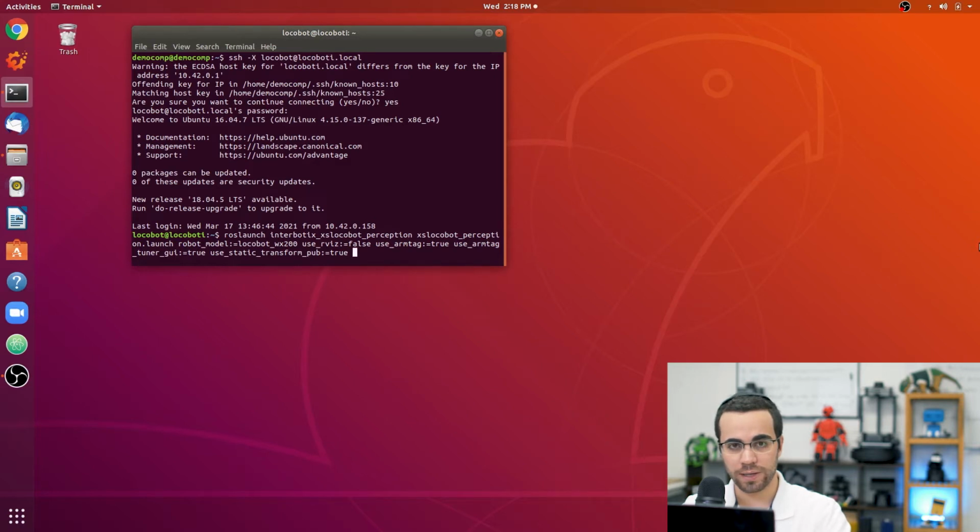As you might know from the standalone arm vision kits that we did a tutorial on, the ArmTag related nodes are there so that you can figure out where the arm is with respect to the camera. In the case of the LoCoBots, though, we already have a URDF that defines this, so we don't really need to do calibration. The only reason you'd want to do it is if maybe you want to get some better accuracy, finding out what the pose is of the AR tag with the camera directly, because there could be some error when it comes to the actual build of the physical LoCoBot, or maybe the AR tag is placed slightly off center on the AR tag plate. In general, I haven't found this to be so much of an issue.